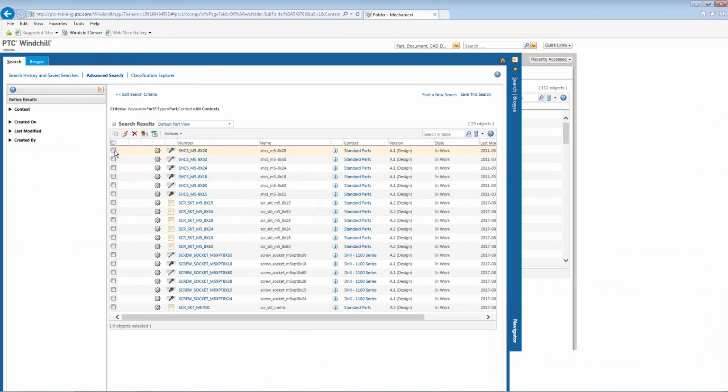So of course, one of the methods that people use is to simply rename them, rename them old, or rename them with do not use on the end of them. However you want to categorize that, you can do that. You can also promote them to an obsolete level, which you may or may not want to do, only because a lot of individuals don't have access to obsolete objects, which means when they pull up an assembly that uses those, they won't be able to pull that assembly up because it can't access those specific files.